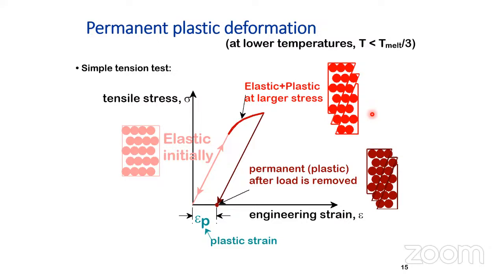Okay. So if you see the graph over here, three types of limits have been given. If you stretch your material up to the force where I have placed the cursor and then remove the force, your material will regain its original shape. But if you increase the stress, or force, again, it will move to this point where plastic deformation occurs. After applying the force again, you will transfer that system to the permanent plastic deformation part.